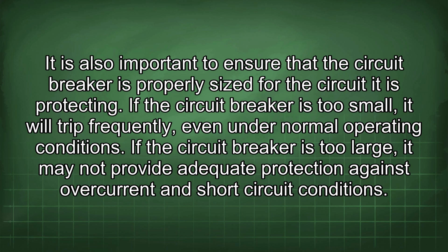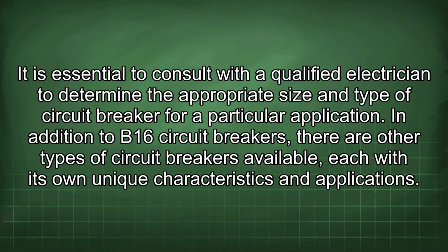It is also important to ensure that the circuit breaker is properly sized for the circuit it is protecting. If the circuit breaker is too small, it will trip frequently, even under normal operating conditions. If the circuit breaker is too large, it may not provide adequate protection against overcurrent and short-circuit conditions. It is essential to consult with a qualified electrician to determine the appropriate size and type of circuit breaker for a particular application.